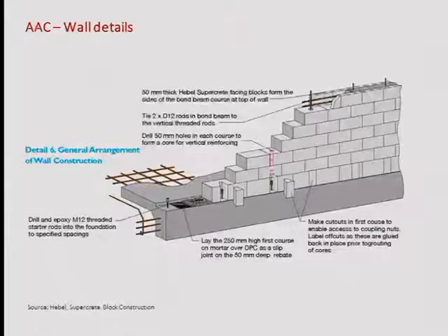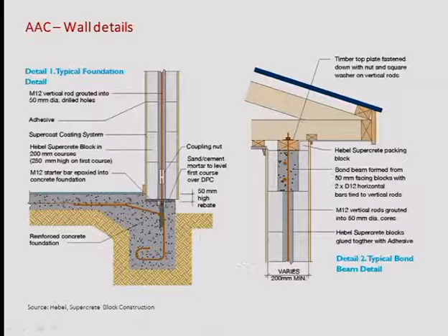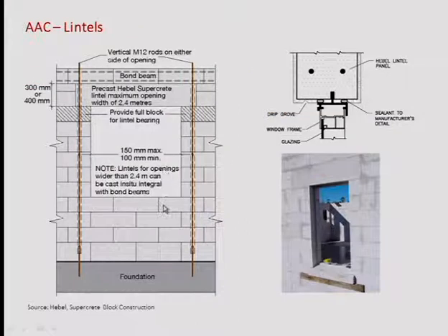And the details are always the same. So you will find reinforcements, single leaves, you see the cutouts with the coupling nuts to connect the vertical reinforcements to the footings. And again, reinforcement embedded in the footings. Structurally speaking, they're not so strong. You won't be able to do a wall out of this without reinforcement. You will always need to place reinforcement rods.